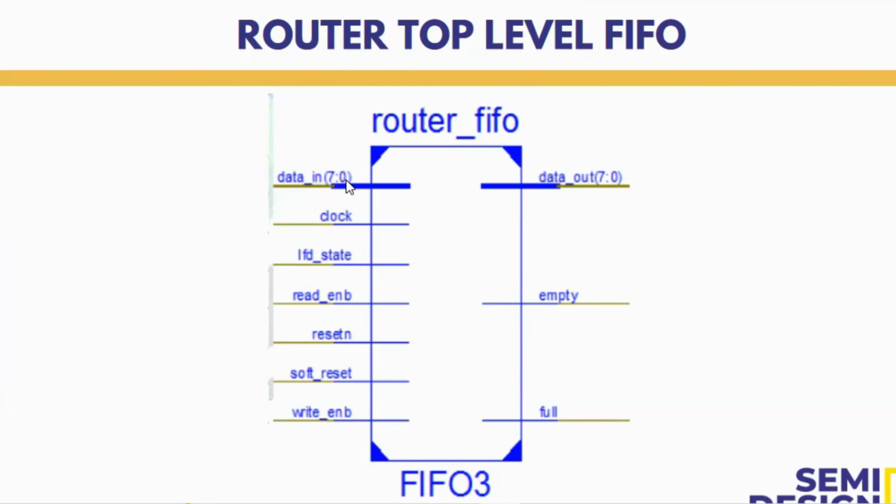In order to differentiate between the header and data, it will append one more bit in the LSB. If the detected data is a header byte, it will append 1 to this data and store it in FIFO. If the data it is detecting is a payload, then it will append 0. So that when the data is being read from this FIFO, it will be easy to differentiate between the address and the actual data. So 9-bit data it will store.